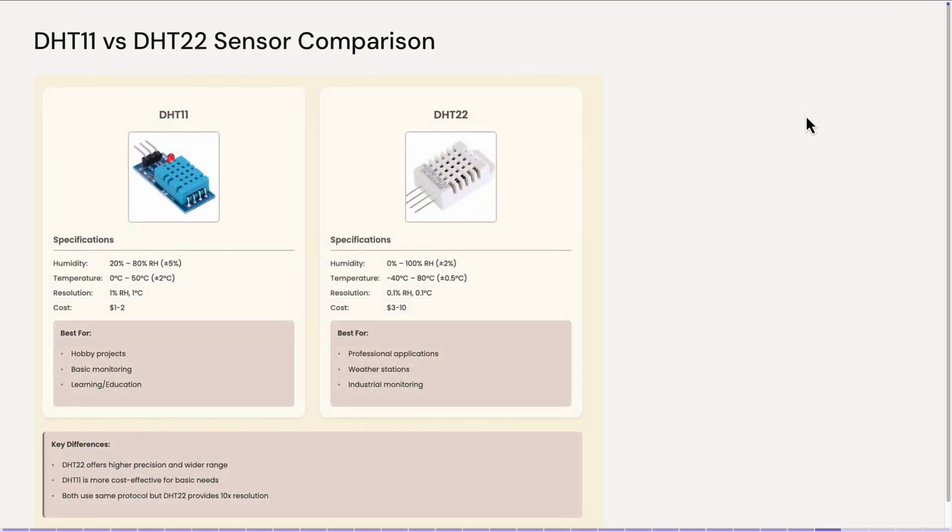And now, for example, for Arduino, you will find two different types of integrated humidity and temperature sensor. This one is the DHT11, and there is also the DHT22. So if we look at the specification, for example of this one, let's talk about the range now. You buy a sensor like the one I have, it can detect humidity between 20% and 80%.